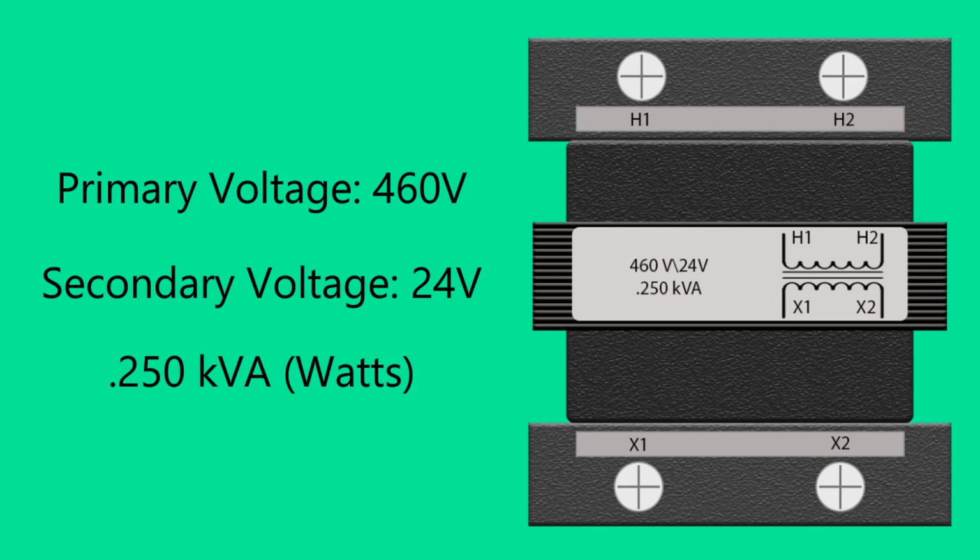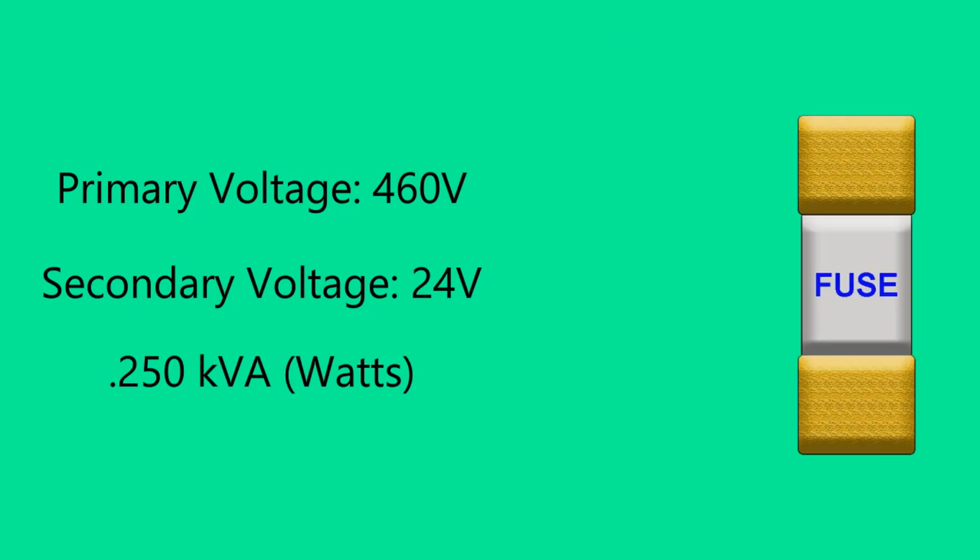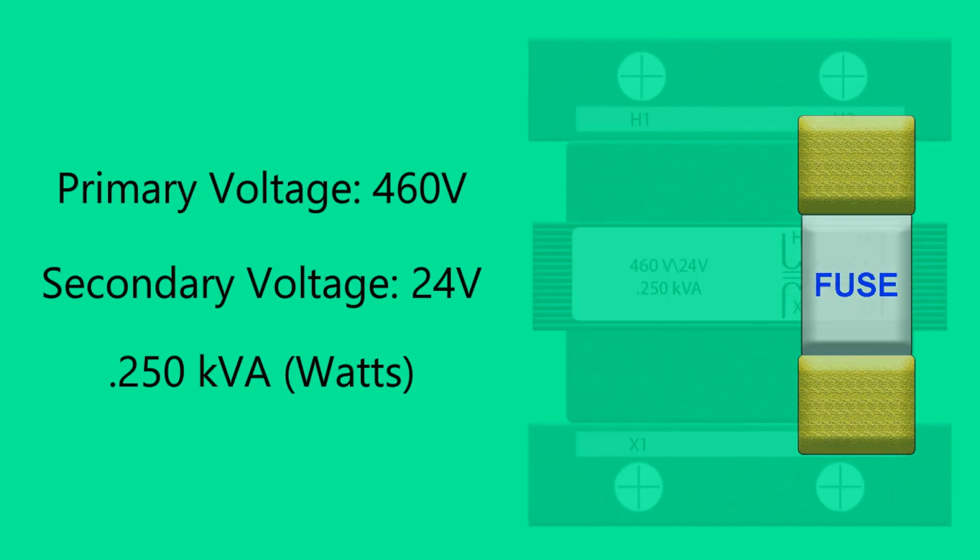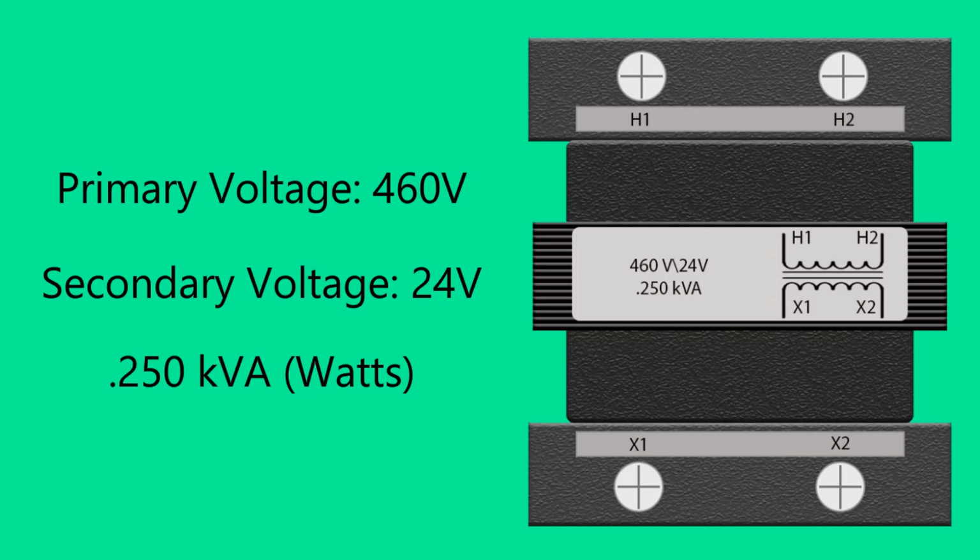The electrical specifications are identified on the transformer: the primary voltage, the secondary voltage, and the wattage. The wattage is listed as VA. The transformer wattage is used to determine the overcurrent protection. Notice that overcurrent protection can be calculated from the primary or secondary voltage. Overcurrent conditions can damage or destroy a transformer.